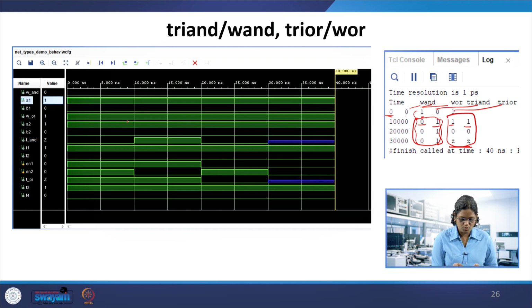This can also be viewed here at 10, then next at 20 and at 30. This is represented in picoseconds, which is why we see 10,000, 20,000 and 30,000, but hash 10, hash 10, hash 20 is given in the circuit.